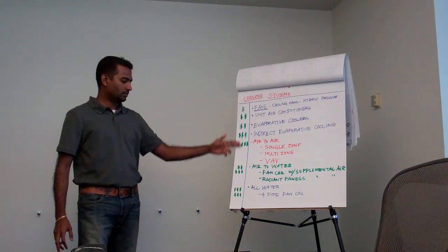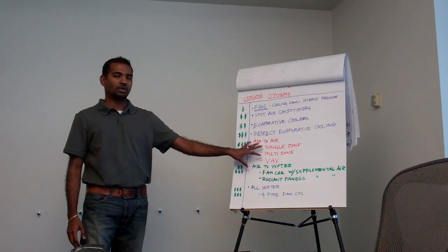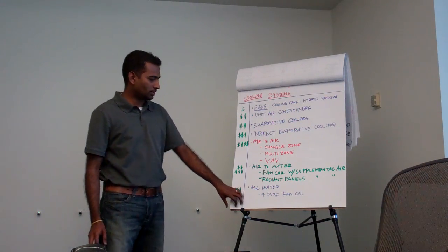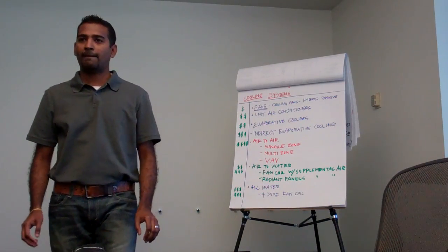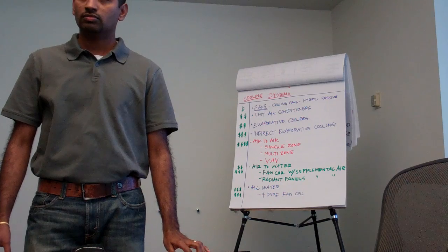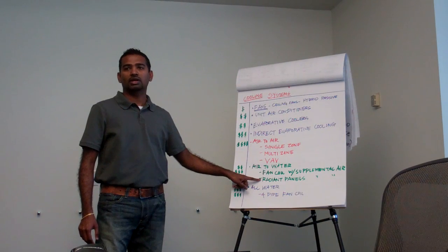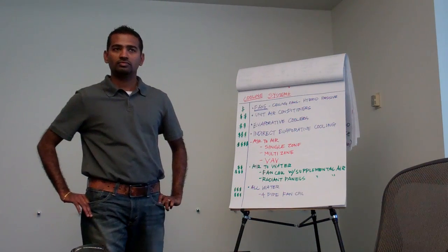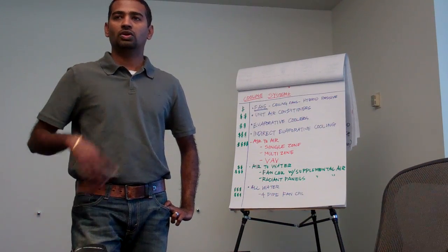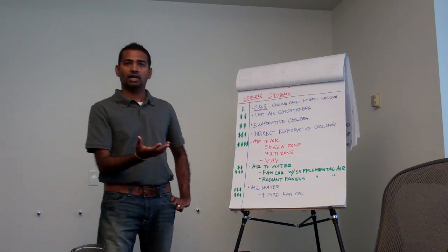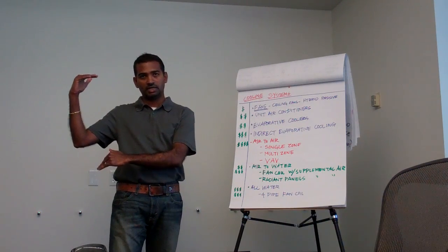So just from a cost standpoint, this is the highest in cost. And most often, we use a mixture of all these things. There are hybrids of all those, correct? Right. One of the things that's become popular are chilled beams. That would be more similar to the radiant panels, the all-water, where you're actually just running water, either hot water or chilled water, through the beams, and they're absorbing the energy from the space or radiating that energy to the space. Correct. So knowing that will change our design a lot. Right. So we have to make sure which system we're planning on doing to take care of that 45% gap.